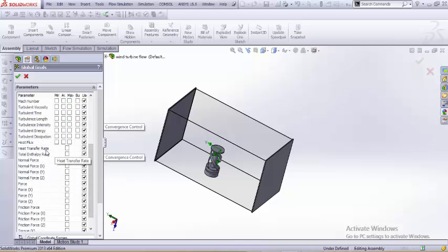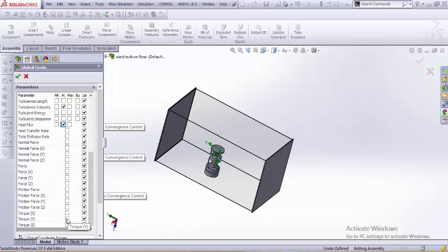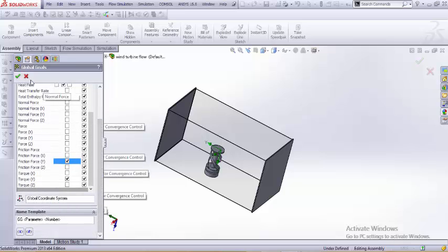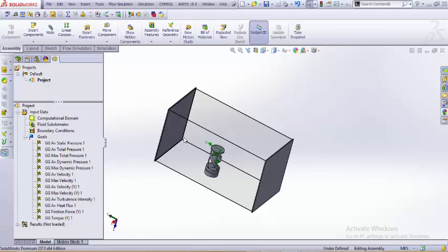We could also look for turbulence intensity, heat fluxes if you want some heat transfer related problems, some forces, frictional forces, torques, frictional forces in Y direction. The more results you want simulated, the more time it would take. And if you want other features like surface frictions, all you need to do is insert surface goals to see what surface parameters you would see.